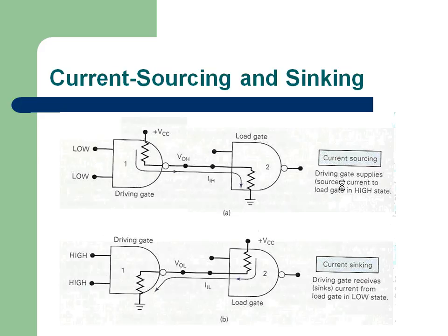Now, a little bit more about this current discussion, current sourcing and sinking. We were discussing a similar example last time. Let us assume a NAND gate where both inputs are low, so the output is obviously high. High means it's a TTL example where current is seen through VCC, through some resistor. So this is a current, and for the gate, this is sinking. So this is sourcing, this is sinking.